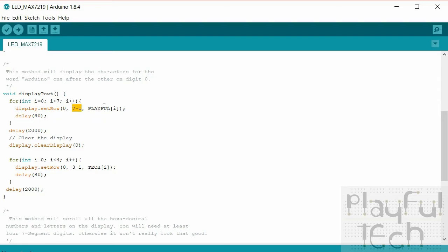So this is a bit confusing, but the character on the furthest right of the display has the index 0, and then the one back from that is 1, 2, 3, 4, 5, 6, 7, etc. So if I want to start at the left-hand edge, I'm going to start at digit 7, and then as I increase, as I count through the letters of the word I'm going to spell, this number actually gets smaller, closer to 0, because the right-handmost character is going to be 0.